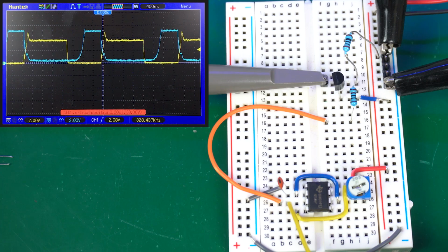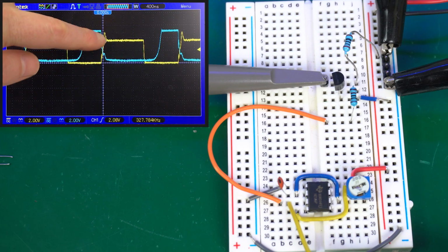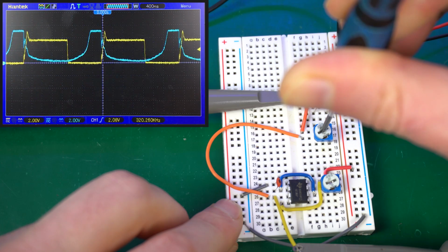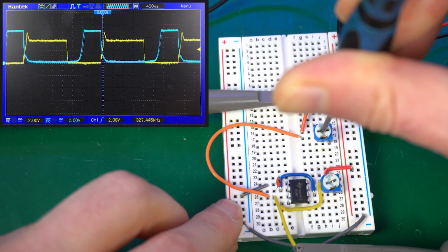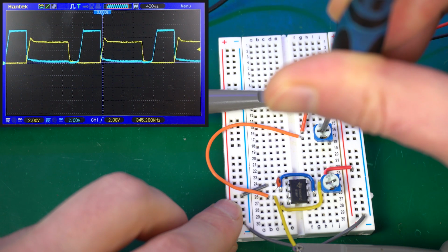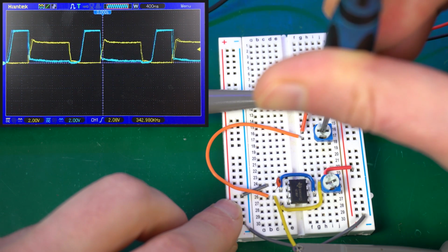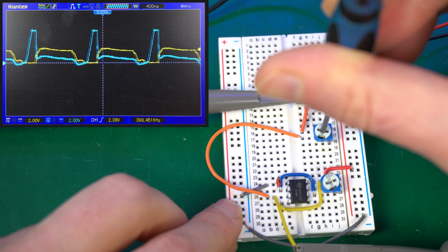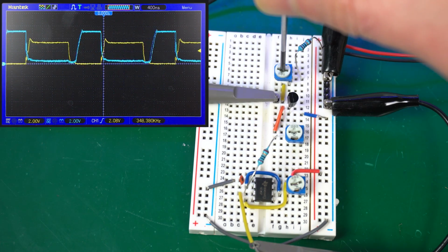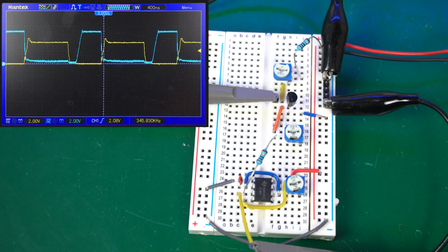The duty cycle of the output wave looks off, with the low period being much longer than the high period, and the edges aren't even sharp, straight transitions the way they should be. Uh-oh. It turns out we can improve the edge transitions by putting an adjustable resistor at the base to limit the current flowing through the transistor just to the right amount. And when we do that, the transitions are much better, but that's not solving the other problem. I can also tweak the resistance into the collector itself, and that again improves things, but it's not perfect.